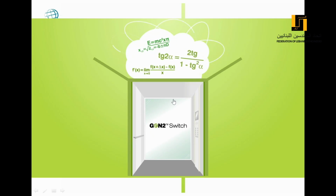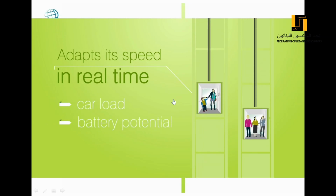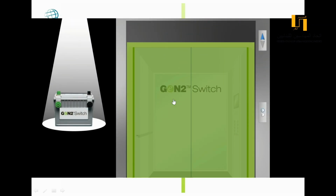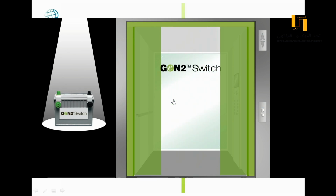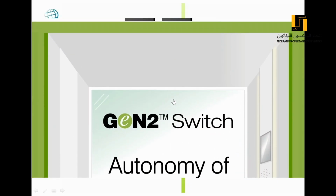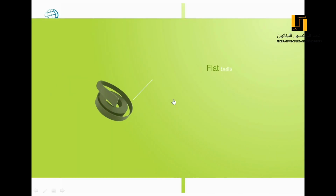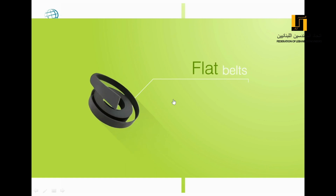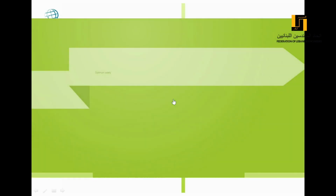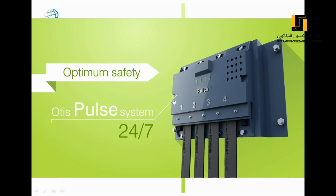Gen 2 switch is a smart elevator. It can adapt its speed in real time depending on the car load, the battery potential, and the trip being made. In case of a power blackout thanks to its batteries, Gen 2 switch can continue to operate on its own in total safety for approximately 100 trips. Gen 2 switch was designed based on a unique technology using flat, steel-reinforced polyurethane belts in place of traditional cables. The belts make the elevator's operation silent and, most of all, reliable. For optimum safety, Gen 2's unique pulse system monitors belt's condition 24/7.